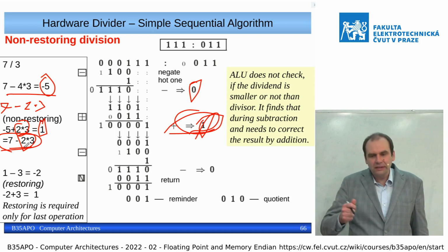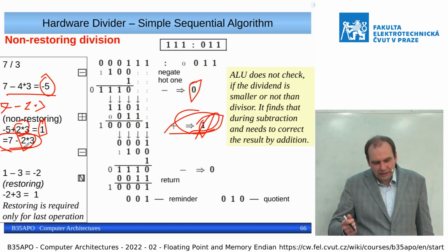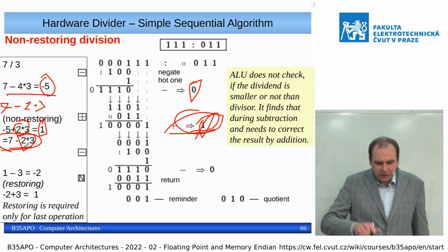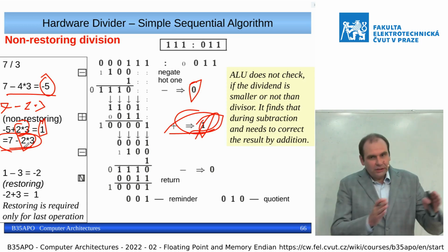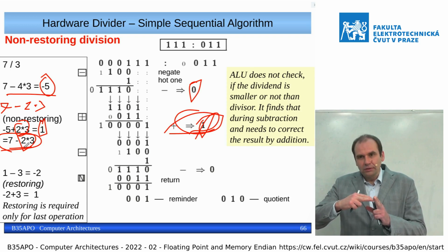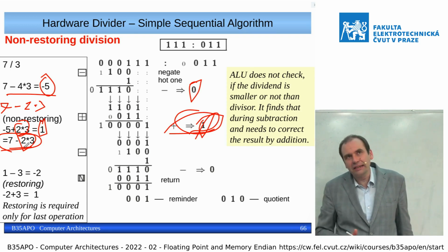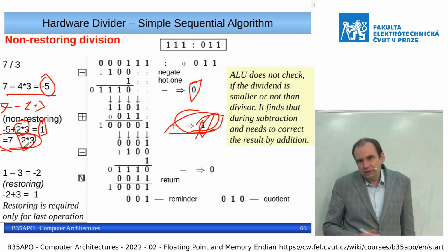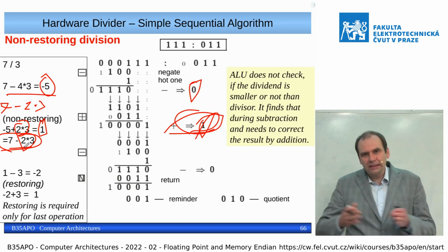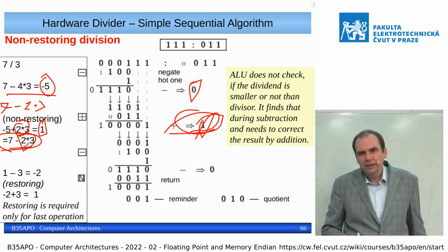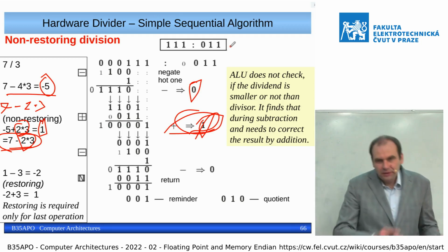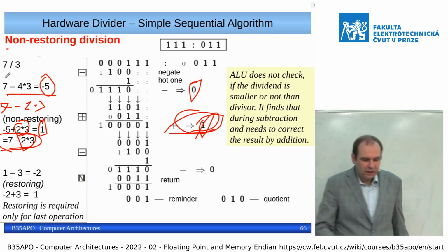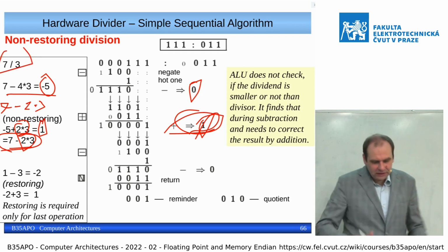And instead of the subtraction, we need to switch between subtraction and addition to basically shift the range around the 0. So basically, it is something like binary search, where you divide the range to 1/2, 1/2, 1/2. So you use 1/2 of the divisor each time and shift the initial value by this attempt.